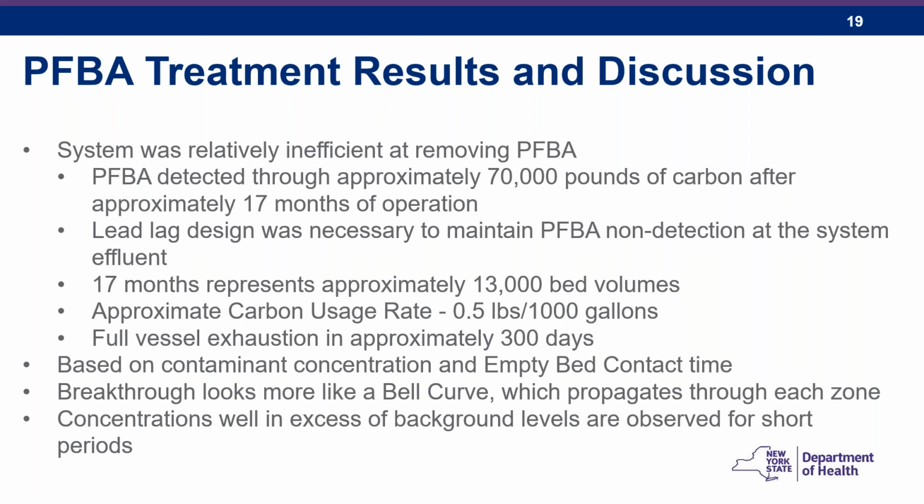we do see competitive sorption, or we do see that the longer chain PFOA compounds are making their way through the contactor and are driving off some of the PFBA that has already been taken up by the contactor, and that would be the mechanism behind why we're seeing increases in the PFBA concentration with time. It's certainly not that the reactor's creating PFBA. There's no background contamination of PFBA in the reactor, but what looks to be happening is that the PFBA that is parked at an uptake site, because PFBA is going to rush out well ahead of the PFOA, those parked PFBA molecules are later being displaced by PFOA as it makes its way through the contactor.